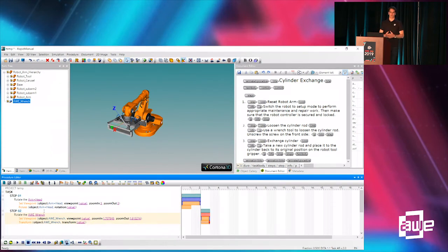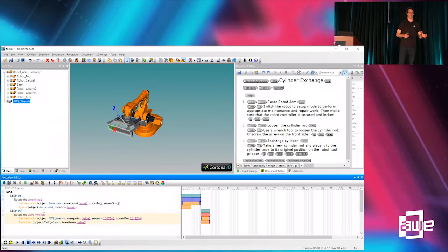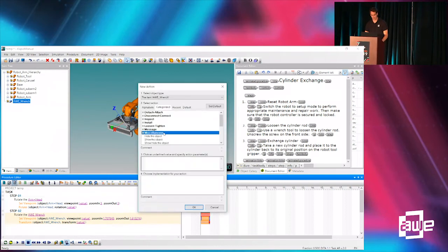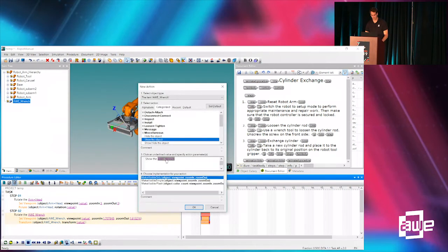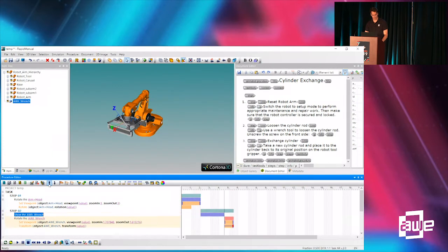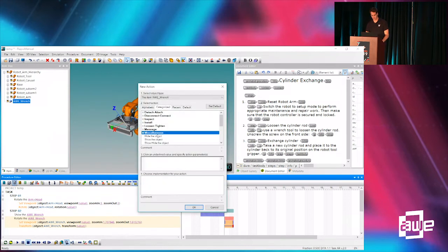Before rotating the tool, I'm just going to make it appear. So then the technician does not always see the tool in augmented reality, but only when it is needed during the steps. So very easy. I add, hide, show the object, this one, make it visible and flash. Perfect. Let's make it appear right before the rotations. And once the rotation is done, I'm going to make this tool disappear.